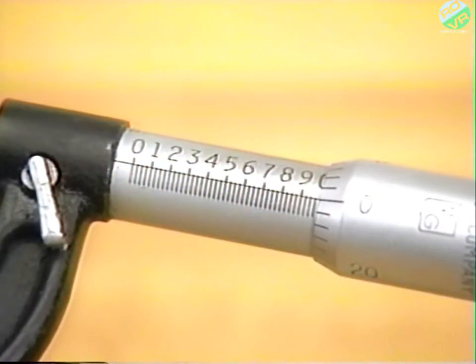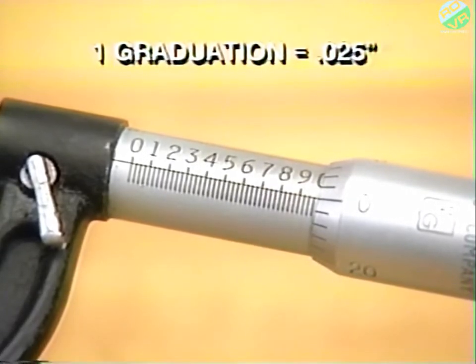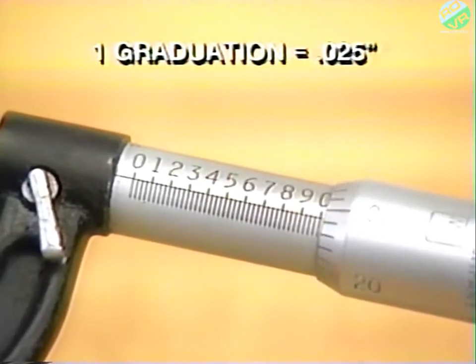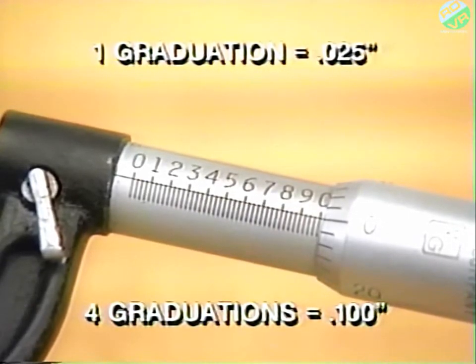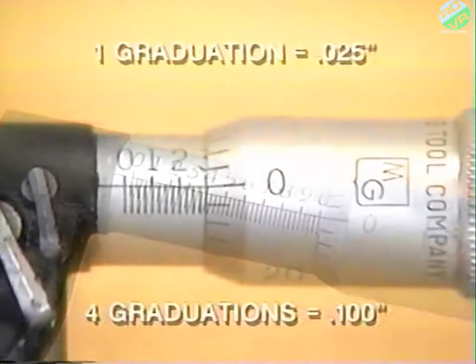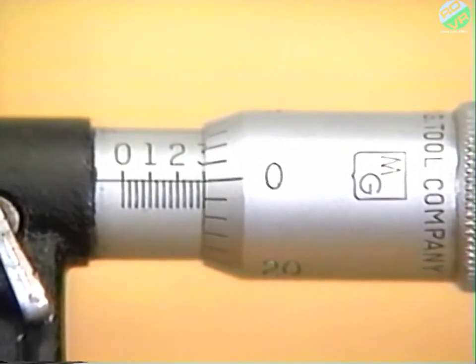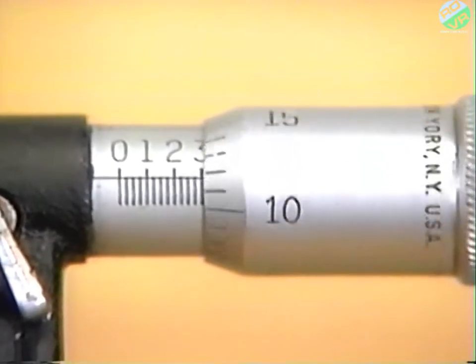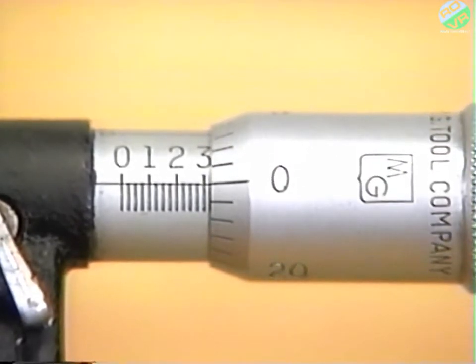A scale on the sleeve of a micrometer reading in inches is divided into 40 graduations, each one equal to 25/1000ths of an inch. Every revolution of the thimble uncovers one division on the sleeve. Every fourth division represents 1/10 of an inch and is numbered. The beveled edge of the thimble is marked in 25 divisions. Each division represents 1/1000th of an inch. So one rotation of the thimble moves the spindle 25/1000ths of an inch.